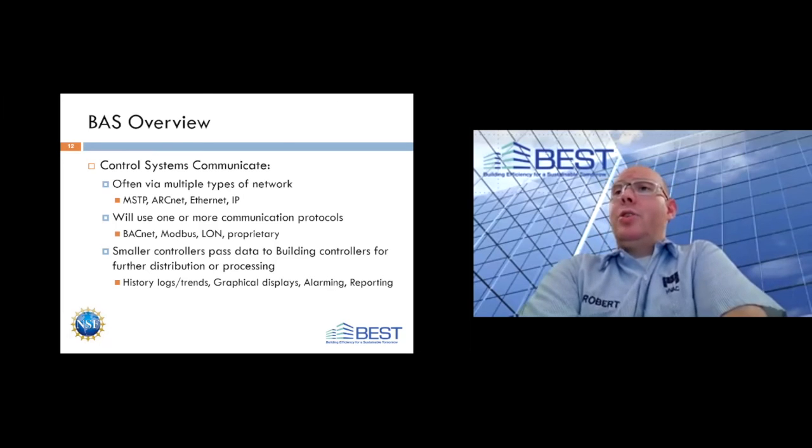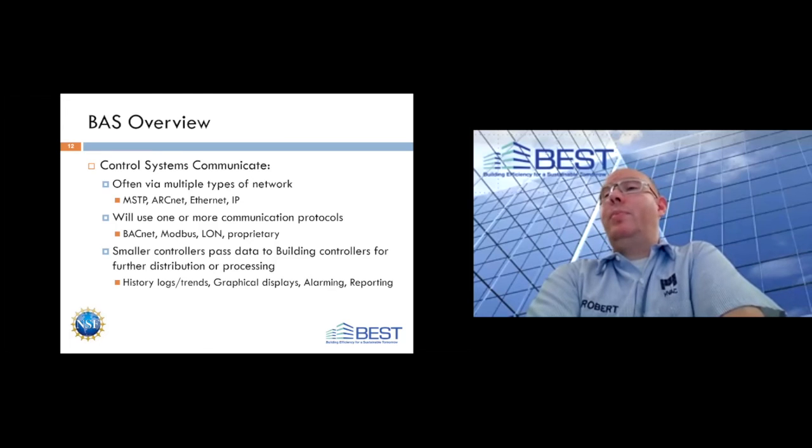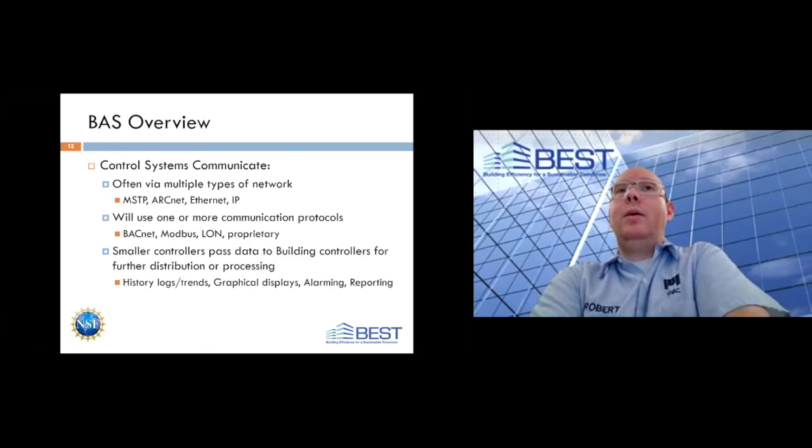Modbus is also a very common protocol, well, all over the world. You'll run into Modbus as direct communication with boilers, power control systems, computer room air conditioners. These types of systems love Modbus. It is a very low-cost, easy to implement, very reliable communication protocol. Not super user-friendly from the configuration standpoint. There's much more work associated with it than there is with BACnet or LON.